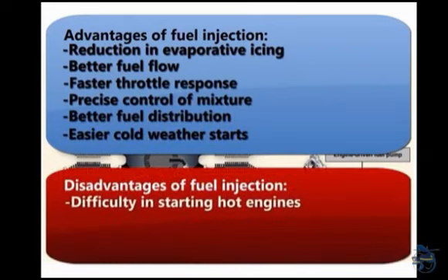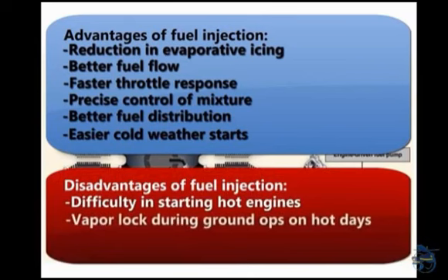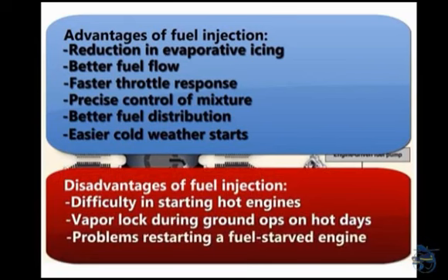Disadvantages: difficulty in starting a hot engine, vapor locks during ground operations on hot days, problems associated with restarting an engine that quits because of fuel starvation.